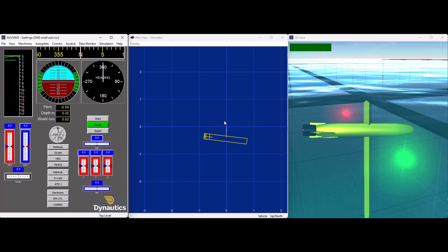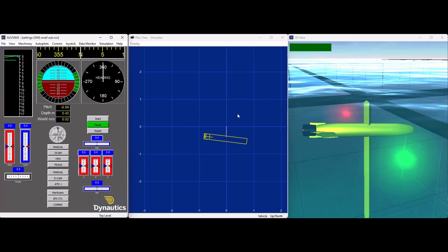We'd like to use the wireframe in 3D view to check that we've defined the elements correctly. For instance, that the hydroplanes pivot around the correct axis. In order to do that, it's useful to set up sliders on the instrument panel which link to the individual controls.